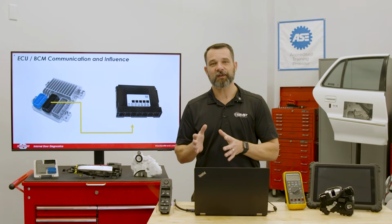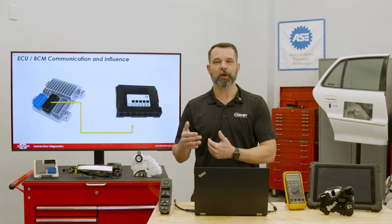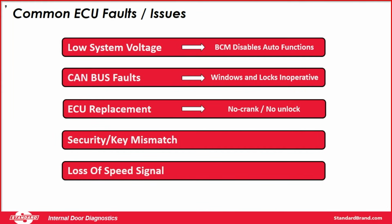So I think it's fair to say that these systems are very dependent on good communication and properly working modules, both in the door itself as well as in the dash. And so some common issues where the ECU affects the door or the window operation. If we have a low system voltage, we can see where the BCM might disable auto functions. If we have CAN bus faults, we can see where windows and locks might become inoperative. If we had an ECU replacement requiring any type of programming where the programming failed, we could see a no crank or a no unlock situation.